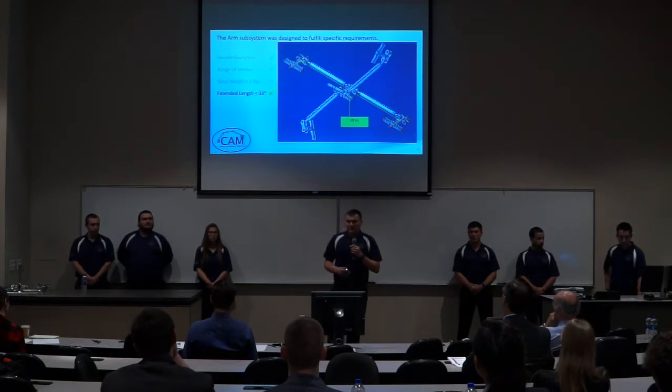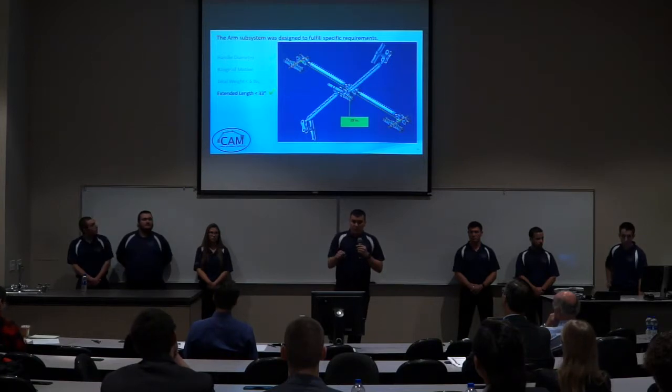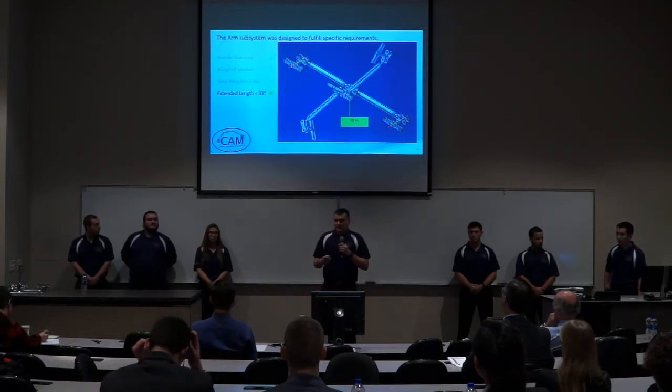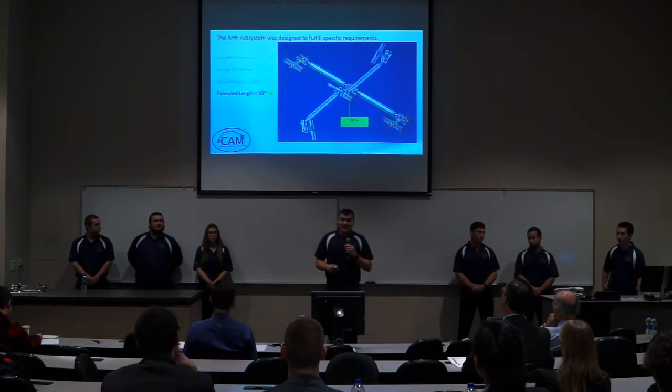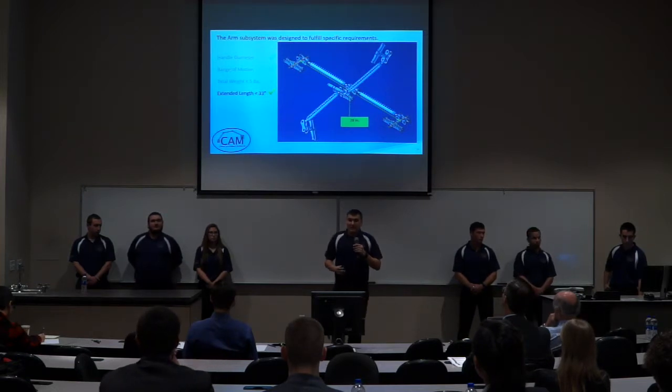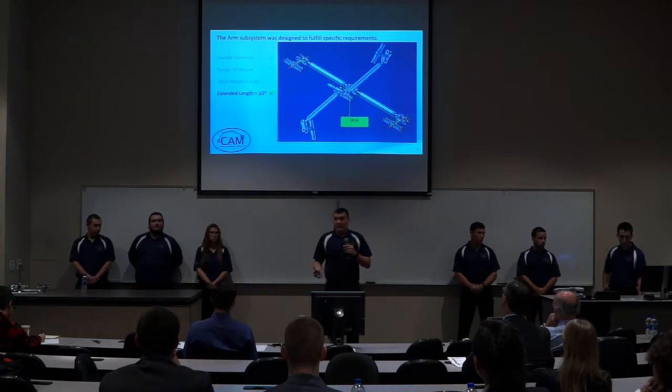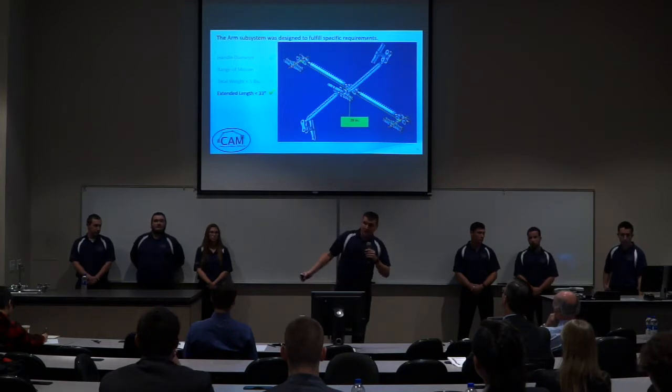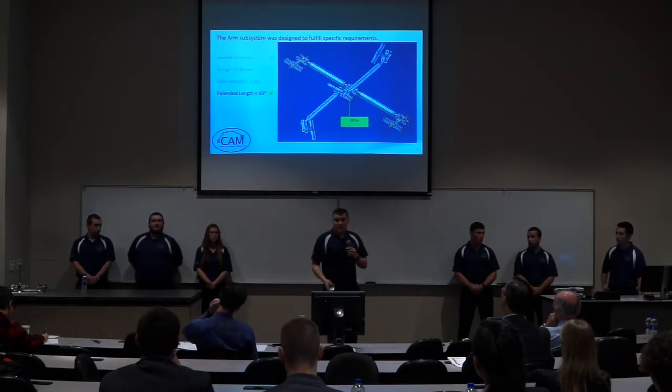This is another requirement that we implemented just to ensure that the total length of the arm would not be past arm's reach when totally extended. So as you can see in the graphic, we come in at 28 inches, measured from handle center to handle center. And that ensures that even when at maximum extension, the handles won't be out of reach, so you won't have to reach farther than you would have to adjust that.